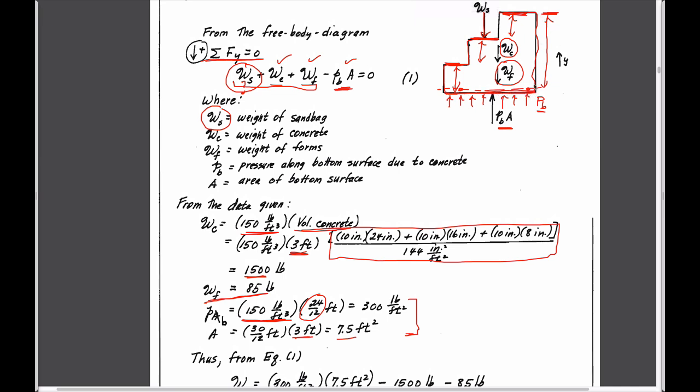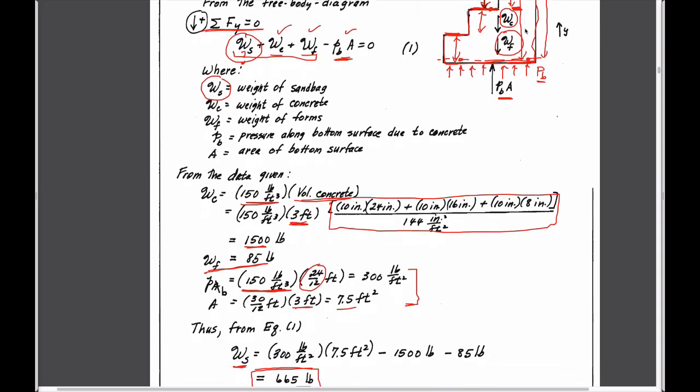Its magnitude is given by the maximum height of the fluid here, because this is atmospheric here. Clearly the magnitude of pressure here is basically equal to the height of concrete that we have here. So the pressure acting here is not 0, but it is acting as 0 here. Hence the pressure acting at the base is equal to this height. Okay?